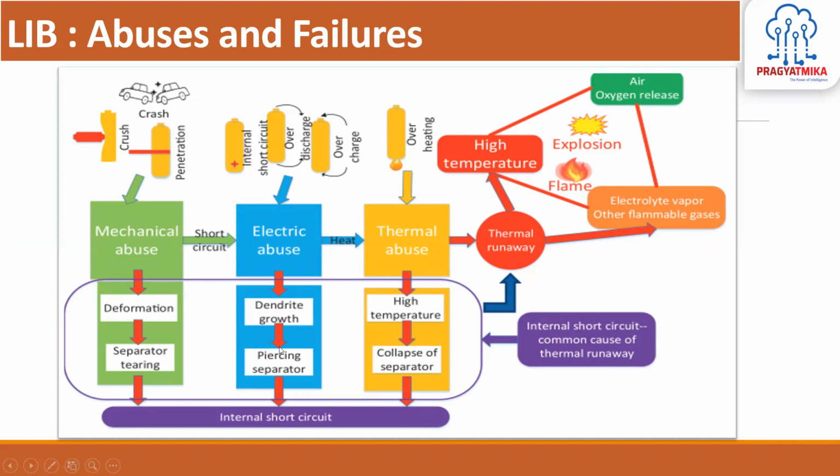It will happen if you do excess charging, overcharging or over discharging of your pack. 20% to 90% is the generic SOC standard we need to follow. But if you charge up to 100%, or discharge your pack below 20%, the health of your pack will be lost fast, and these things will come faster. That's the abuse that you are doing.